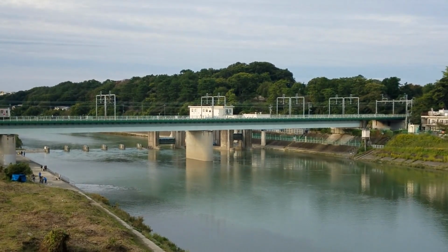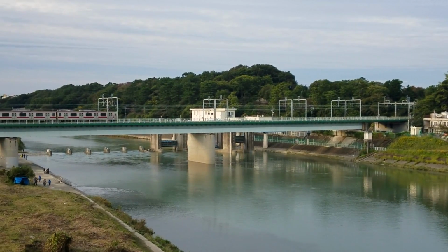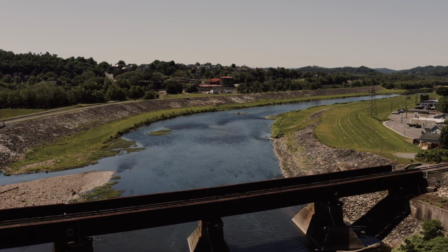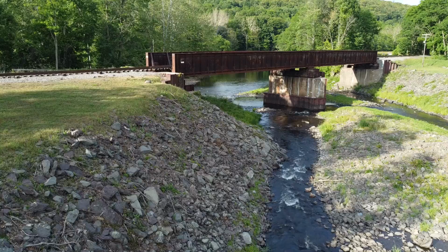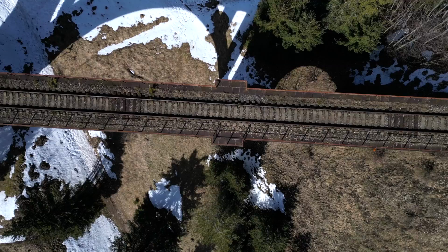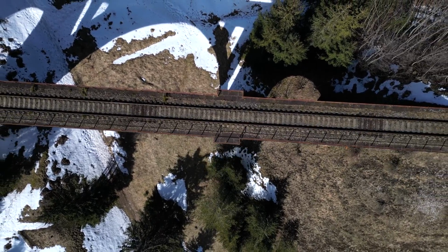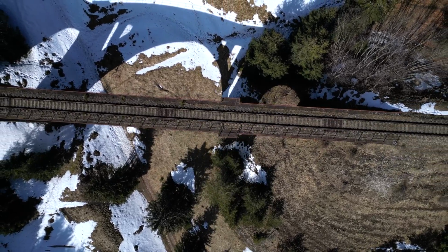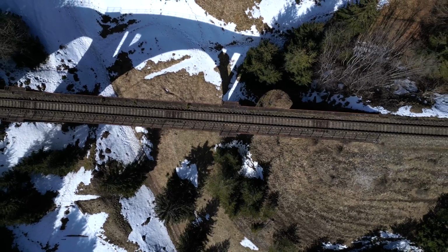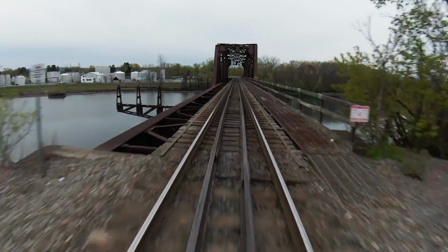Metal decks. Maintain the steel surfaces for corrosion and fatigue. Inspect the interfaces and the fastenings regularly. Respect the tamping limits and remember to be aware of expansion. Check bearing condition if they're present. Bearings allow the movement between the bridge and the substructure, and if these seize or degrade, the stresses are transferred onto that track above.